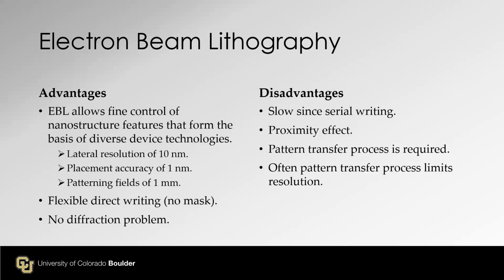It's serial writing. No mask, but you have to expose, not quite one by one, but yes, you have to. The beam needs to move around to expose. It's very different from the mask alignment concept. And we have to deal with the proximity effect. I hope I have time to cover it at the end.